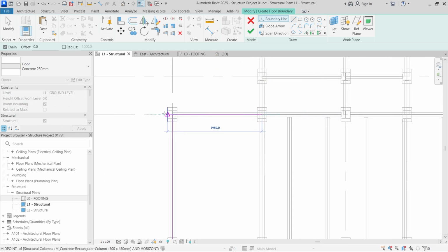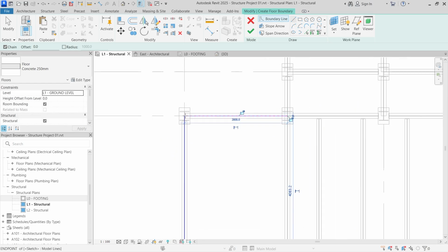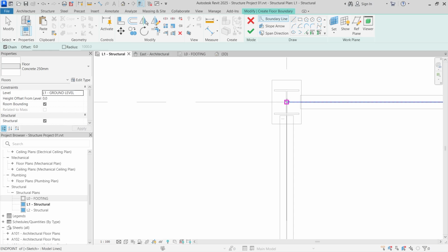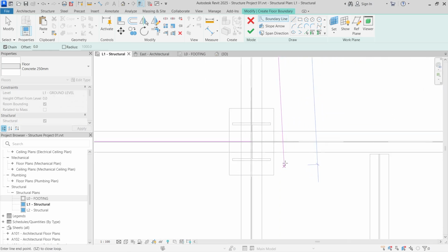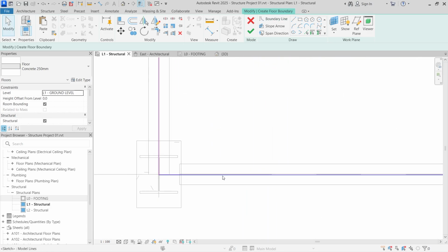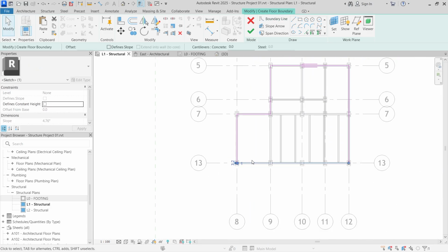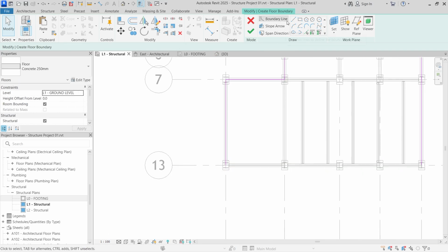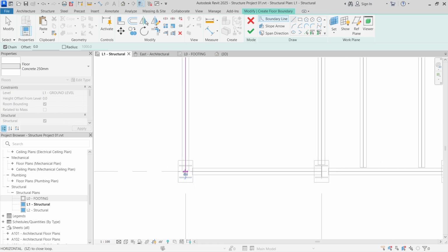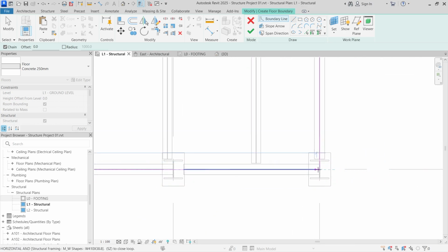You have to make sure you are exactly at the center line, or else it's not going to connect for some reason. So we have one more point to actually do here, center line. If Revit doesn't show you the square, then it's not yet at the end point. So that's what you need to have in mind. We're just going to go ahead and delete this one because I don't think it's correct. I'm going to use the draw line again. Endpoint to endpoint.